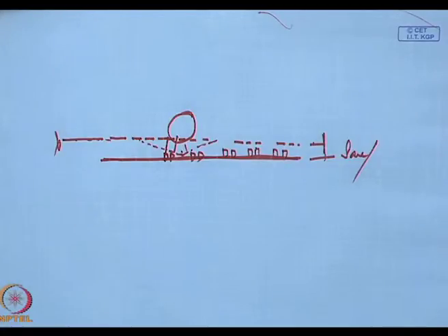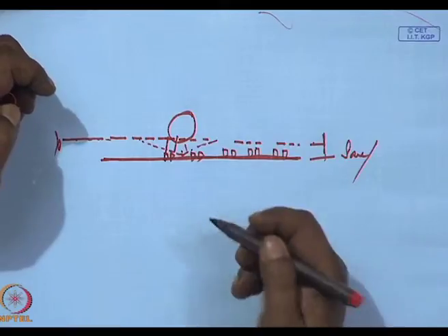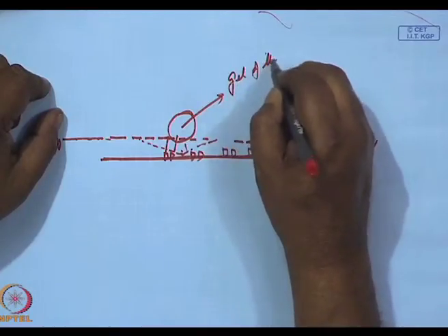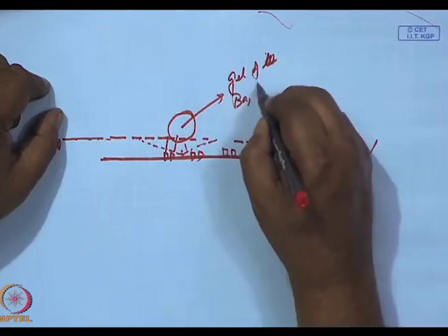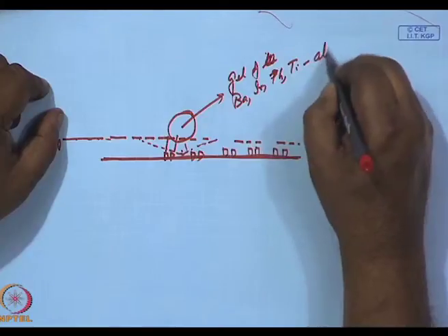Now, alkoxide based sol gel technology has used this particular process to have patterns printed on substrates. It can be flexible substrates, it can be hard substrates, but this printing technique is used extensively. Here, this particular material is the gel of, say, what I was using, barium, strontium, lead, titanium alkoxides.